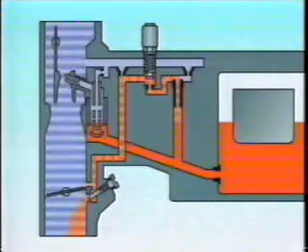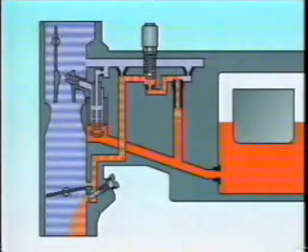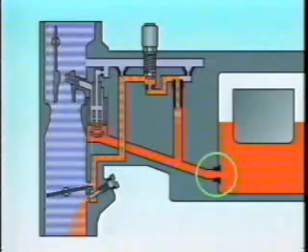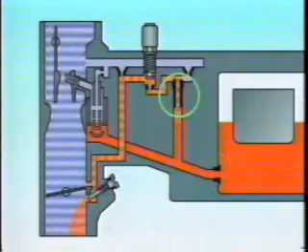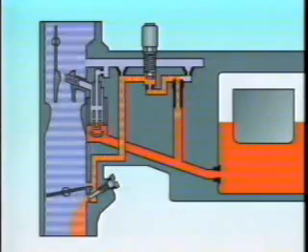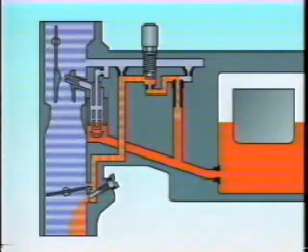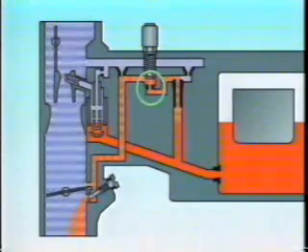The actual flow of the fuel is as follows. It leaves the float chamber and passes through the main jet, then through the slow jet, which controls its volume. It then goes to the primary air bleeder, where it is mixed with air, and then to the economizer jet, where the volume is further controlled.